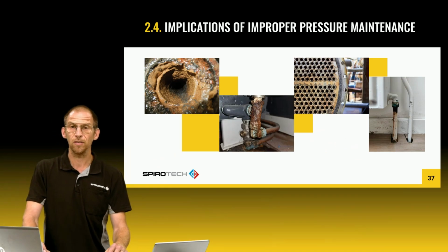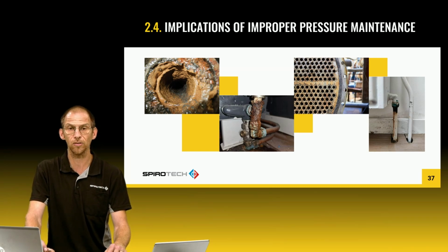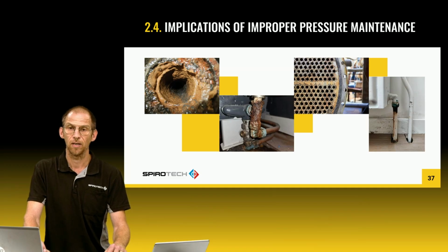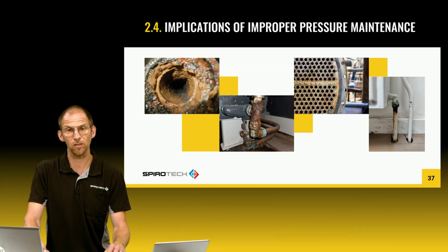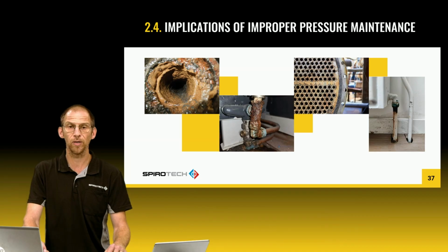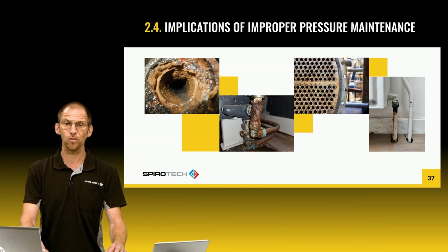When air is drawn in, oxygen enters the circuit. Oxygen drives corrosion of steel components, so radiators, pipework and heat exchangers, and forms magnetite, and you'll also see gas pockets. The consequences of this are worse water quality, reduced heat transfer, clogging of emitters, valves, strainers, pump wear and higher maintenance costs. But the root cause is here: suction side pressure below atmospheric, as shown on a previous slide.